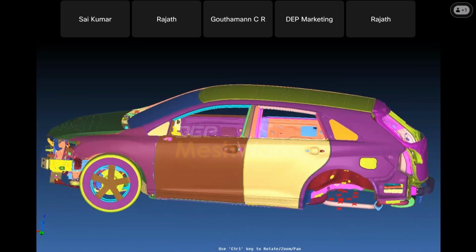Here in the modeling module, we have this ROM panel. Here we have various cases for ROM, Nastran, Abaqus, LS-DYNA, depending on whatever load cases you want to solve for. I'll go with the reduced order modeling LS-DYNA. In this we have three sections which are needed for this ROM creation. First is block creation. I'll go to create block. So I'll put this in a view.